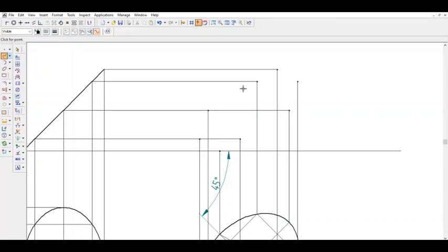Now how to use curve is, first left click. The left click and right click of the mouse are very important. Suppose I am starting it from here, so first click is based on the first point, second point. Whenever you are moving, the curve is also moving there, so make sure that you are aware of that. Third point, fourth point.